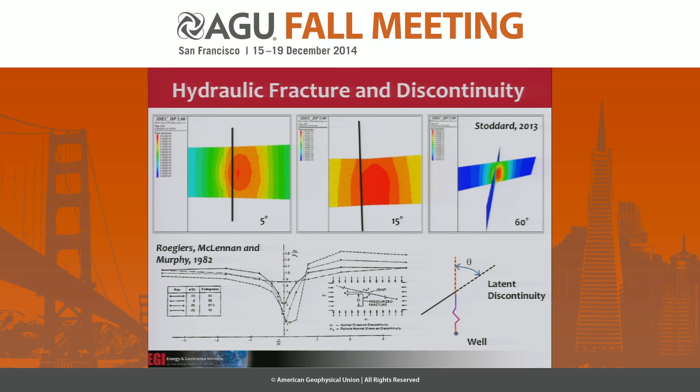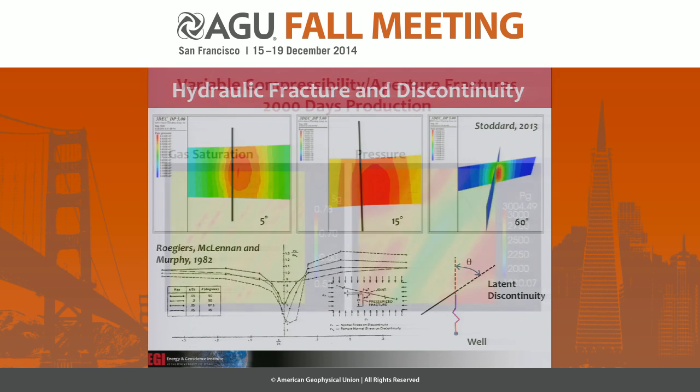Now, there are two cases where this is relevant. Say the Bakken formation that we often hear about. In the Bakken, if fractures grow out of zone, then basically you can be pumping hundreds of thousands of gallons of fluid that are fundamentally not going to do any good for your production. Alternatively, in the Vaca Muerta in South America, you have a fabulous reservoir that extends over maybe 1,000 feet. But fractures may not grow that full 1,000 feet because of the energy dissipation once hydraulic fractures hit these particular boundaries. And I think we'll hear more about this in another talk today.